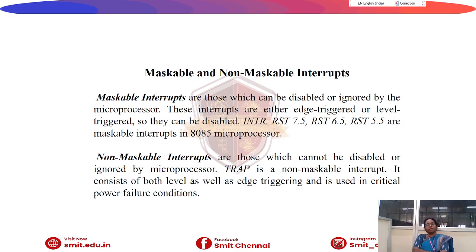Maskable and non-maskable interrupts. Maskable interrupts are those which can be disabled or ignored by the microprocessor. These interrupts are either edge triggered or level triggered, so they can be disabled. INTR, RST 7.5, RST 6.5, RST 5.5 are the maskable interrupts in the 8085 microprocessor.